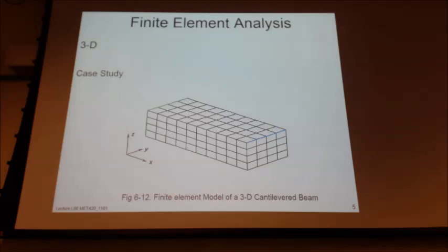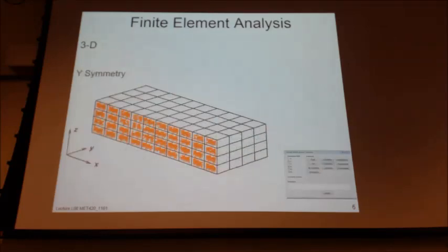When we're looking at the software, it has symmetry buttons for the constraints, right? So when you're determining what your symmetry is, you have to look at the plane that your surface is in. In this example, our plane is the XZ plane, and so we know that our object is being mirrored about that plane, or the x-axis, if you will. And so anything normal to the XZ plane is symmetrical, right?